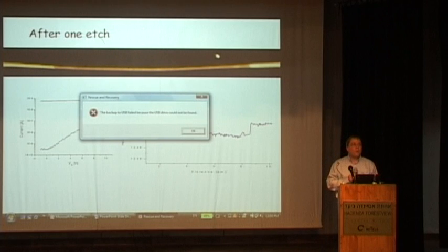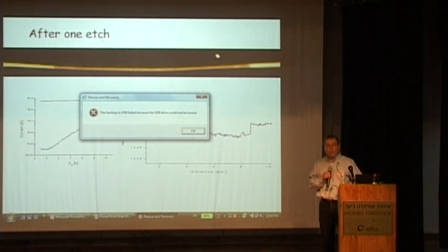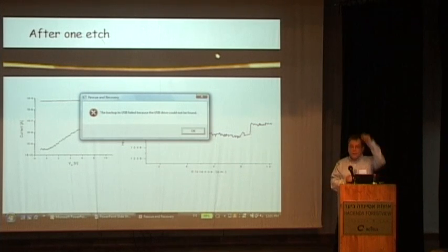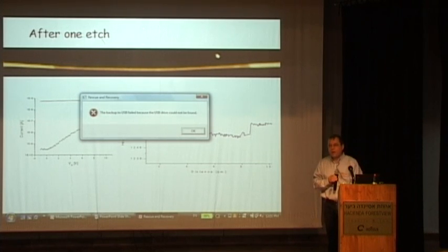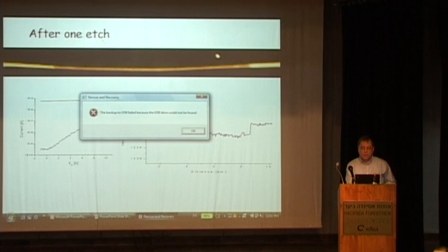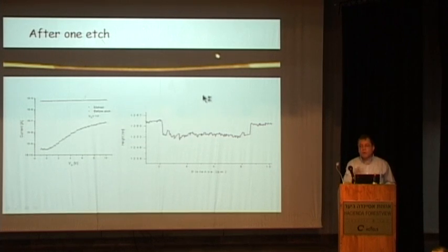I don't know if people have done it, but by SIMS you cannot get this radial distribution, and SIMS also inserts a lot of damage. Profiling by SIMS in a 20 or 30 nanometer diameter wire is a problem. But you're right, if you want, with SIMS you can measure many wires together.